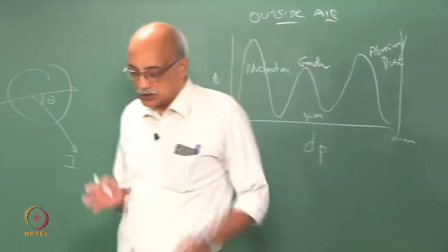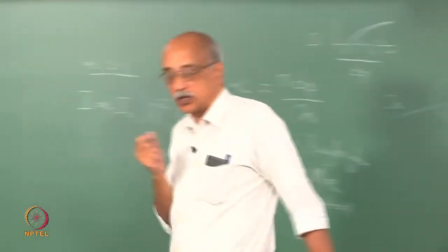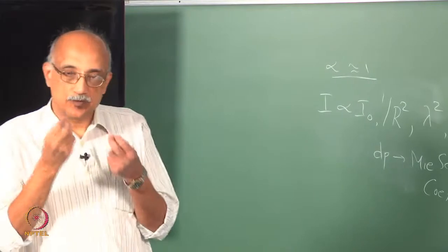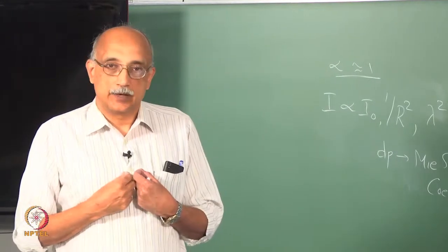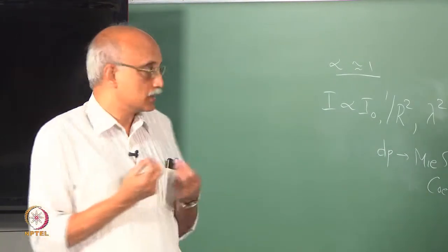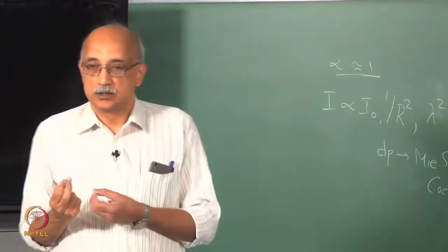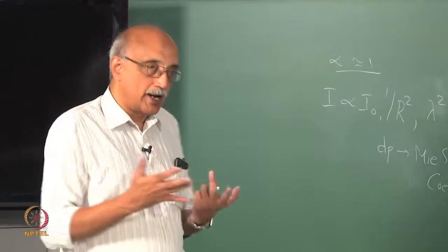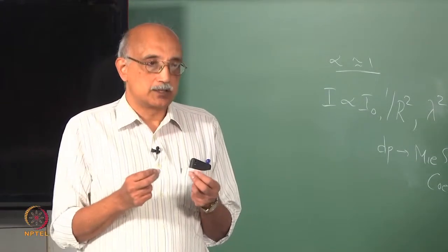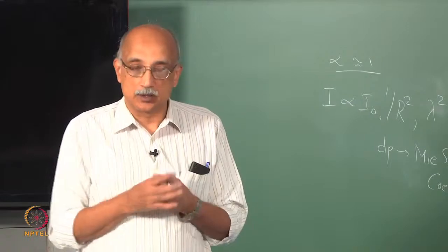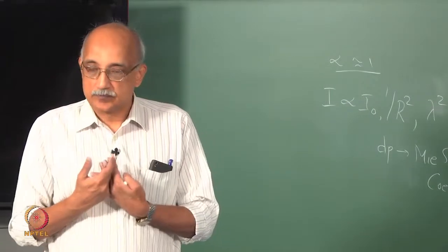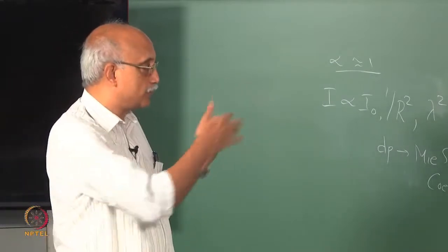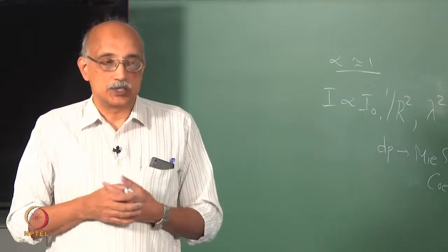So, what happens is in the finest size range the first particles form because vapors condense and form very, very fine nuclei, right, and these nuclei are the first suspended particles that appear in the environment. Then what happens? The nucleated droplets or very fine solid particles start to find each other and slowly start agglomerating, and that is called the growth phase, and that is how we move from the nano dimensions to the micron dimensions.